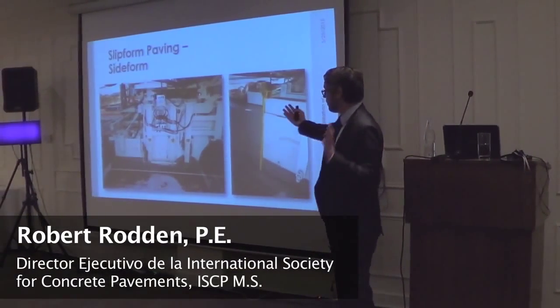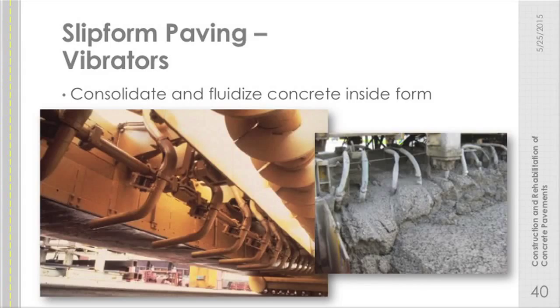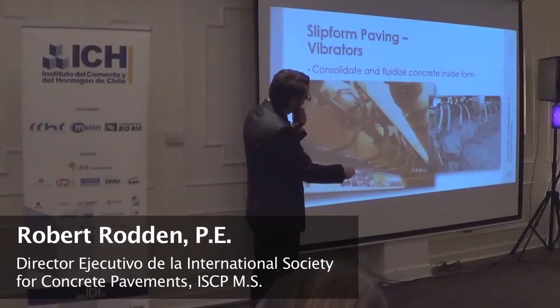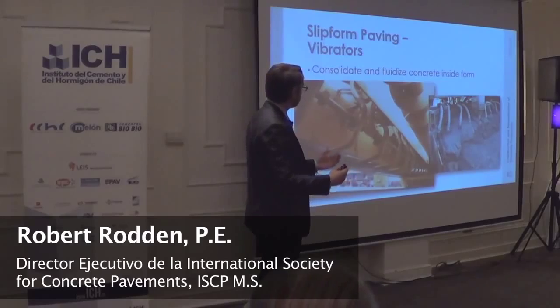So the side forms contain the concrete, the vibrators as a system uniformly spaced with the frequency matching the paving speed even, temporarily fluidize the concrete. So we have our rolling head here. Concrete becomes a liquid, side forms hold it in.